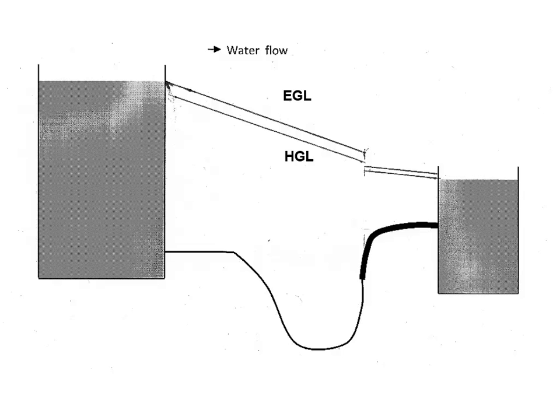When I put a problem like this on a quiz or an exam, what I'm looking for is certain indicators. Maybe I'd assign 1 point if you showed that the slope was steeper for the small pipe than the other pipe. And maybe 1 point that you have to have the EGL above the water surface, that it doesn't terminate into the water surface, but the EGL is above it.